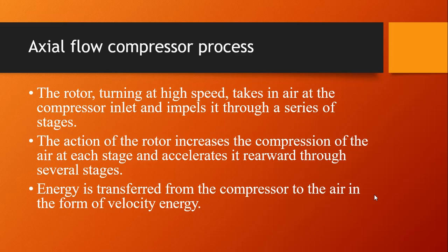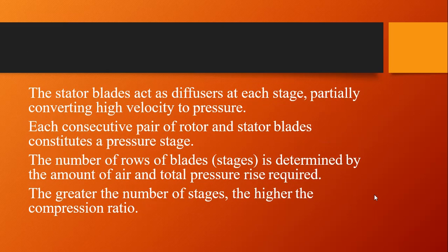Energy is transferred from the compressor to the air in the form of velocity energy. The stator blades act as diffusers at each stage, partially converting high velocity to pressure. Each consecutive pair of rotor and stator blades constitutes a pressure stage.